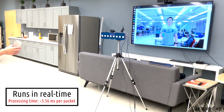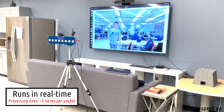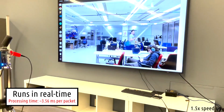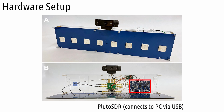Here is a clip showing the system running in real time as the user moves around holding a phone. The system overlays the calculated angle of arrival onto the camera feed as shown on the TV screen. The blue dot indicates the angle of arrival of the BLE packets transmitted off the smartphone. The antenna array hardware has 8 patch antennas connected to an RF switch controlled by a free-running Teensy. The output of the RF switch is collected by a Pluto SDR at 2 MHz sampling rate. The sample data stream is sent to a desktop computer via a USB cable for signal processing.